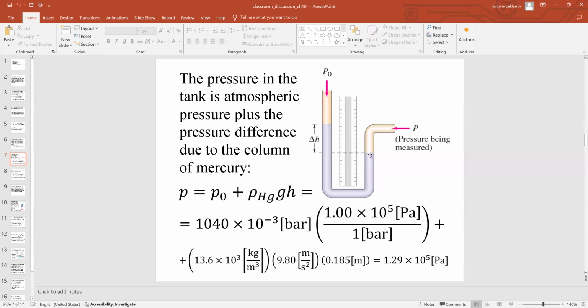That means that this pressure is enough to push the mercury downward, and because of Pascal's principle, all that extra pressure is transported all the way, and the other side rises to a certain level, so you can measure it and do the calculations.